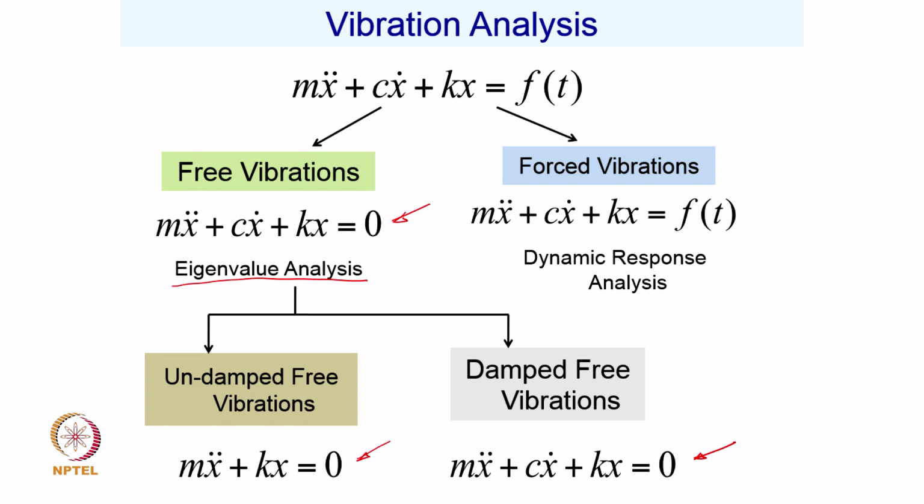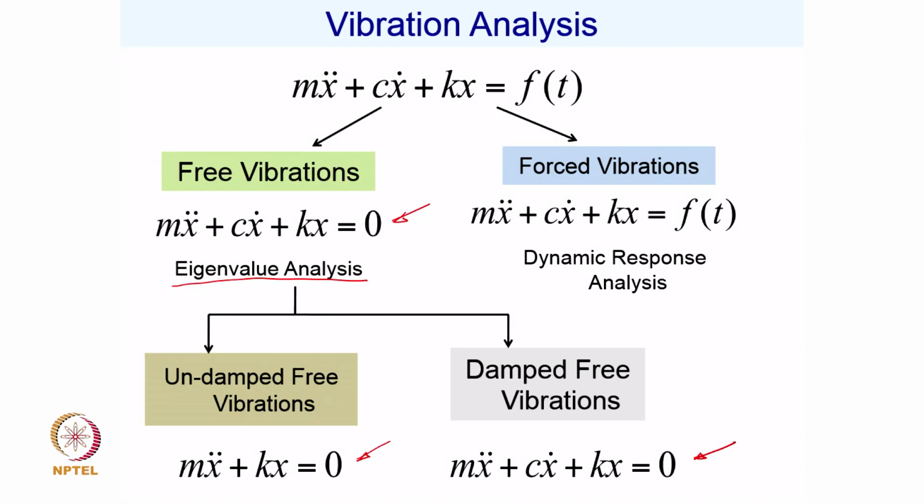Now, you would think that since all our mechanical systems do have a forcing function or excitation inherent, and without that, typically 90+% of your mechanical systems make no sense, they do always have an inherent forcing function, because all of them do have rotating elements, and then there will always be an unbalanced excitation force.